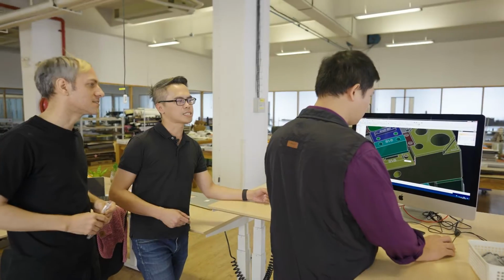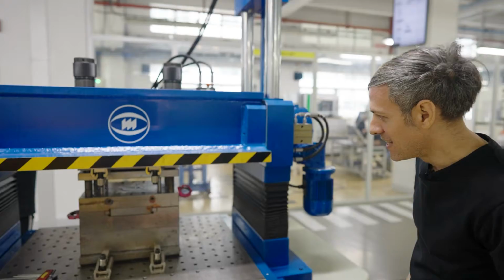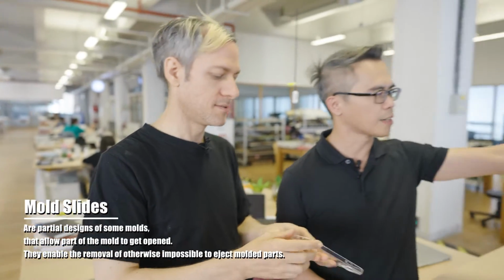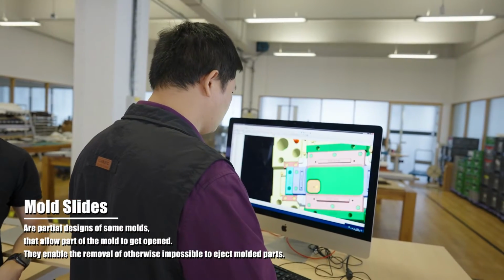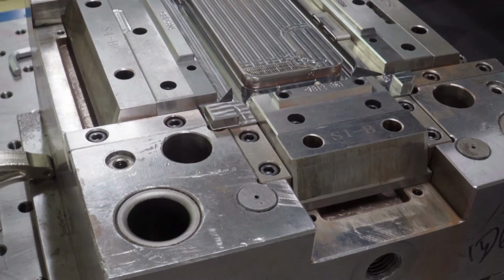Okay, here is our design center, and actually this guy is doing all the mold design for us. It's just separating the different parts. Basically, the mold has two halves, right? Yeah, it is. And I think basically you try to design the part so it works well with two halves coming apart, and then every time you have some feature that won't work with those two halves, you have to have a slide. Yeah, so you can see we have slides around the mold. And actually, for this kind of mold, the designer needs a lot of experience in this field.